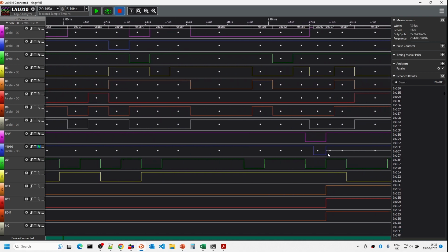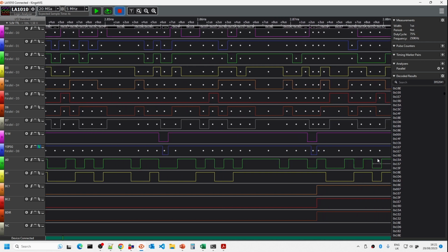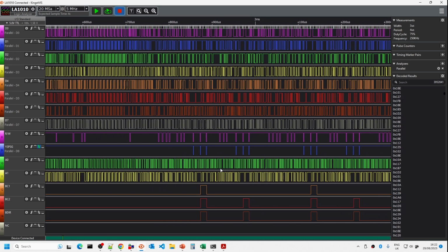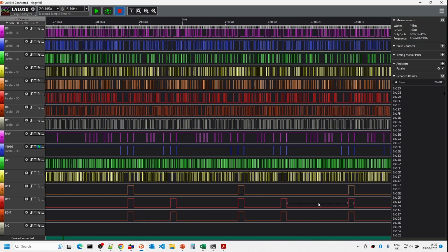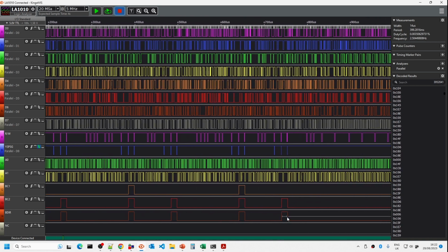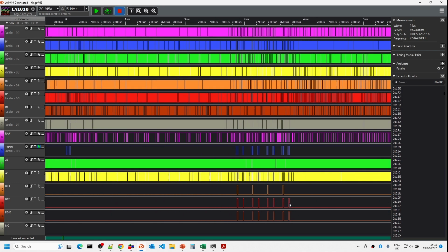Then we've got various other signals going out, so 0, 7. And then you can see here that as a result of that, the bus signals are going high there, so that probably means we're latching the address that we want to talk to. And you can see here that we've got further updates occurring. So the fact that we're actually getting some sound out of here indicates that this is probably working.